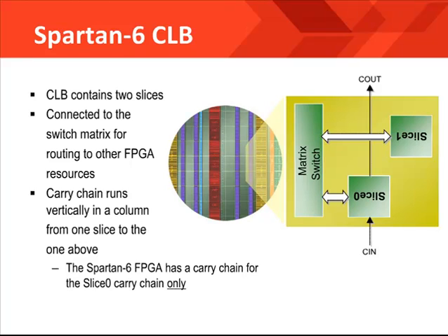The slice resources are the most essential and fundamental to an FPGA design. They include LUTs and registers. LUTs are built to create your combinatorial logic resources, and each has an associated register with it. The LUTs and registers are grouped into slices, which also have other resources.